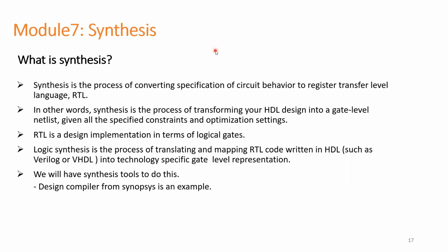In the synthesis process, we will give all the design constraints such as clock definition, clock input, output, and external delay. If there are any interface blocks, we need to do clock budgeting also. We need to take the latency as well. Using all those targets, we need to do synthesis. Design Compiler is the industry standard Synopsys tool used for synthesis.